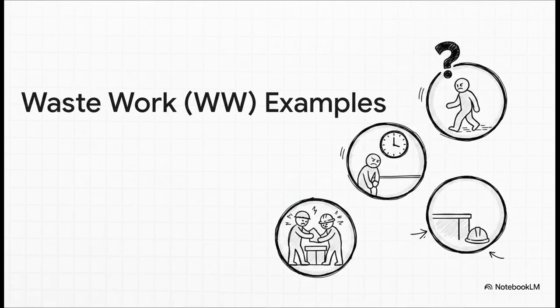And finally, we have waste work, or WW. This is the time that's just gone, completely lost. It's walking around empty-handed, waiting for instructions or materials, being away from the work area, and the absolute worst, having to do rework. Just figuring out what percentage of the day is spent on this stuff is the critical first step to getting that time back.